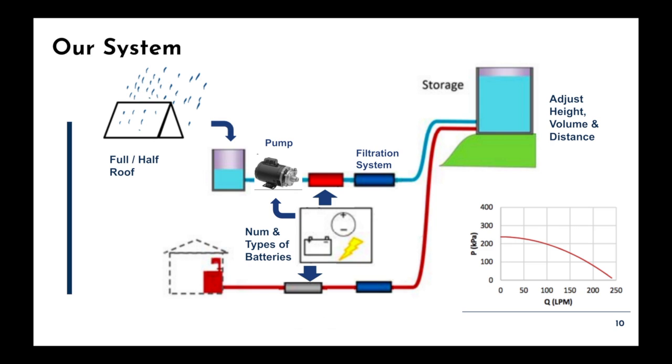The water will be pumped to a storage tank that is located 6 meters in elevation above the catchment tank, 24 meters away from the house. We positioned it in this location so that the water would be able to be fed without a pump back to the house, all powered by gravity. The alternative design considered was to change the elevation of the tank to 8 meters above sea level and 5 meters from the house, which we didn't continue with as it significantly decreased on-demand flow rate.